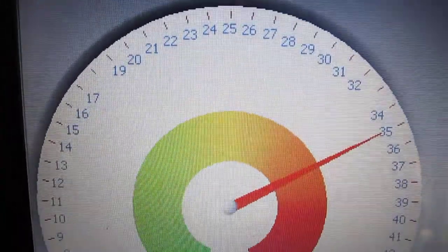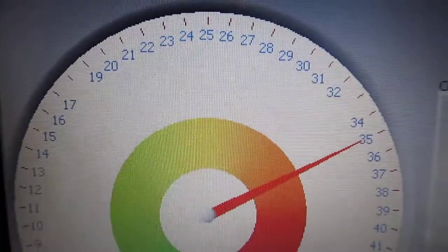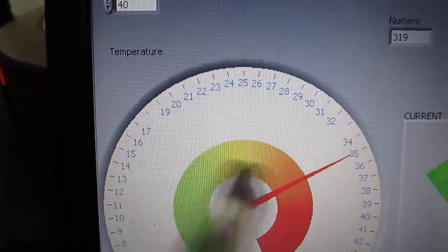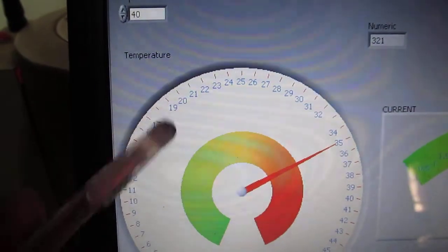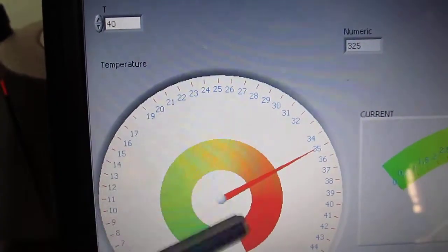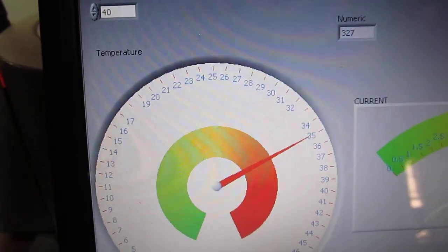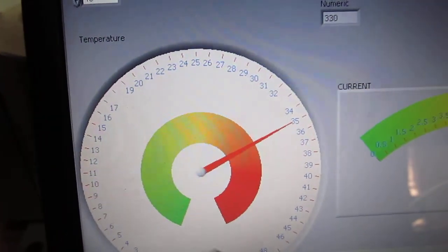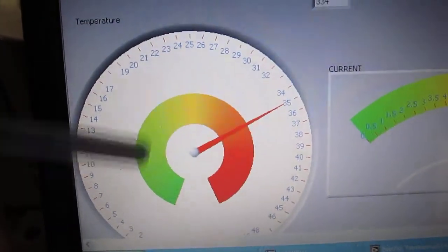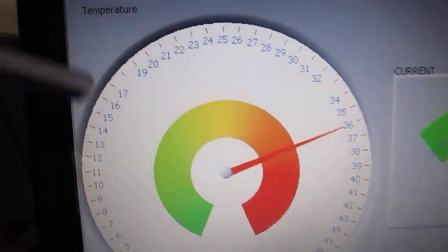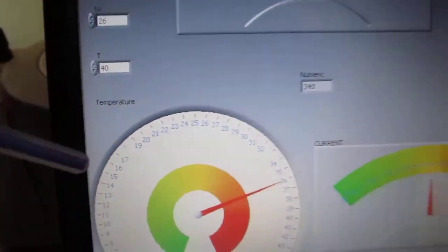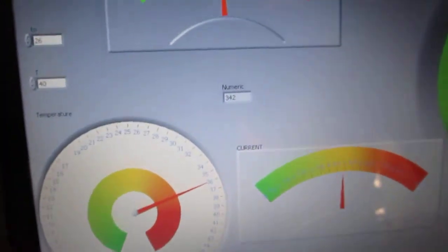In actual operation, whenever a fault occurs, it will draw an enormous amount of current that will rapidly raise the operating temperature of the machine. Even in those conditions, this is going to shut down the motor automatically, so that the operator in the control room knows that there is some kind of fault because of which our motor is tripped, and the indicator shows that the relay has been tripped because of overload. And the operator will come to the motor and resolve the problem.